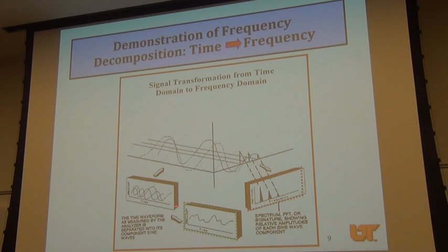So what we do then is make a transformation of the time domain signal into a so-called frequency domain signal. For example, suppose that we have 3 sine waves added here. If I can peel off each of these sine waves from the signal, compute the energy in that signal and plot it, I get a number corresponding to that frequency.